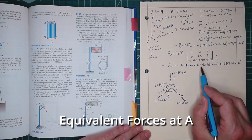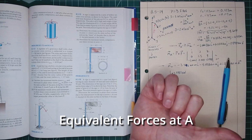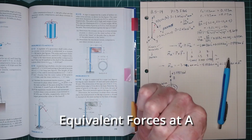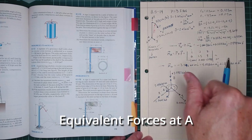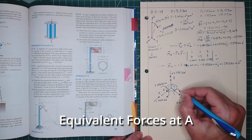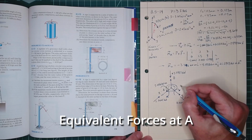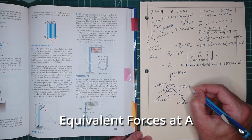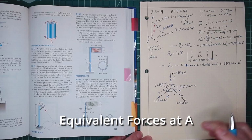If we look at our Y, we have a negative acting about that one. So again, our y-axis is in this direction, positive rotation this way, but it's negative, so it's going to be going in the opposite direction. So we're going to have a rotation going this way, and that is going to be 9.5958 kilonewton meters.